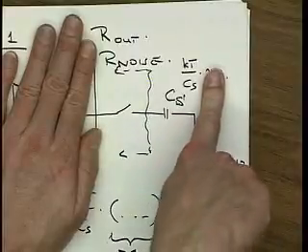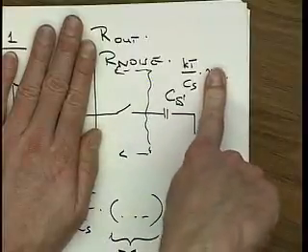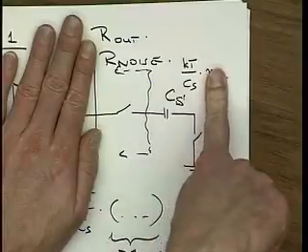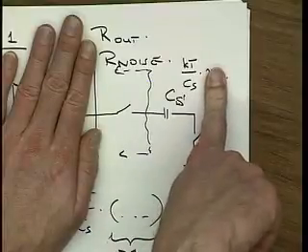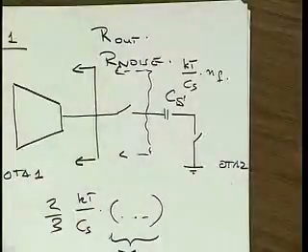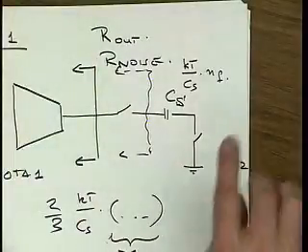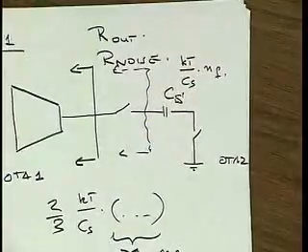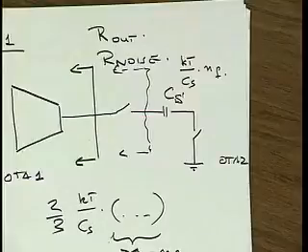But if the user goes and uses a practical amplifier, probably that NF is larger than 1, and so he actually gets worse noise performance. But that's his problem. He has to fix his amplifier. We say, you build the best possible amplifier. That's NF equals 1. The fact that we don't know how to build that amplifier either, well, our competitor specs it the same way.